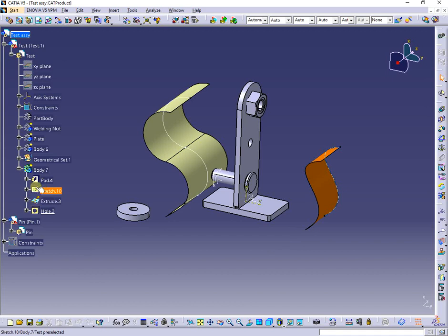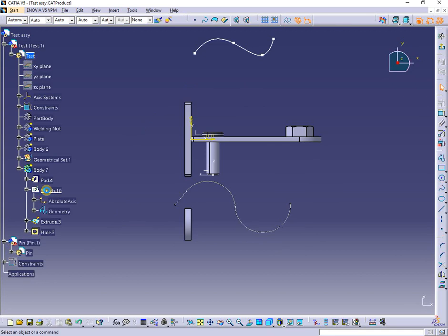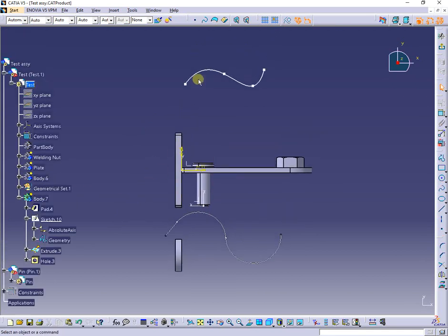You can find different utilities for those options. One of them is when you are editing a sketch directly from the product tree, you can deactivate all geometry visible behind the current sketch that can be difficult to handle another way.